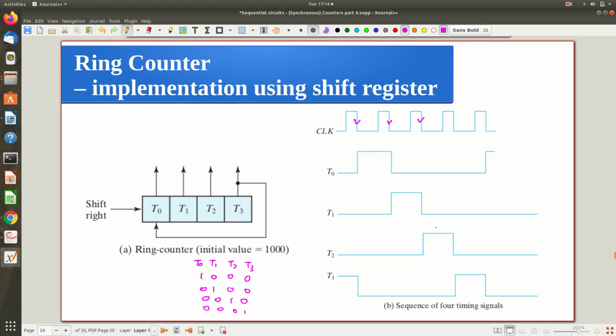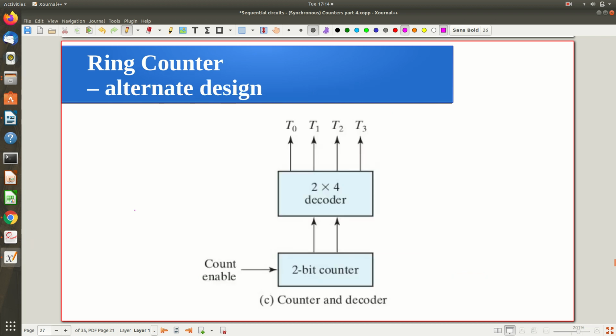So you got this timing diagram, right? It's written clearly in the textbook, and they give the timing diagram also. This timing diagram is equally important. Here it assumes something like a negative edge trigger. That is the way they are drawing the circuit, so accordingly they have written a shift right signal, something like that. If you are applying the clock, it will be something like this. So that is what I understood from the figure, taken from the textbook.